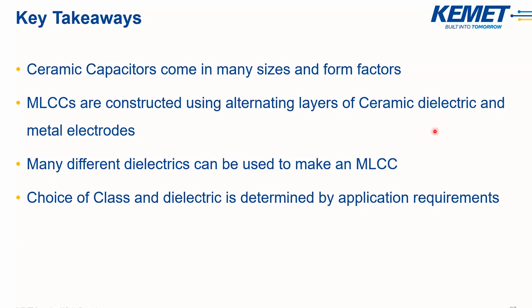Again, MLCCs are constructed using alternating layers of ceramic dielectric and metal electrodes. Many different dielectrics can be used to make MLCCs, so depending on your application, which dielectric you're going to choose. Choice of class and dielectric is determined by your application requirements. So when you approach what capacitor to select, it's good to have all your application considerations: vibration, temperature cycling, maximum and minimum operating temperature, your mission profile. That's really going to guide you to the best selection of the type of ceramic capacitor that you're going to use in your application.